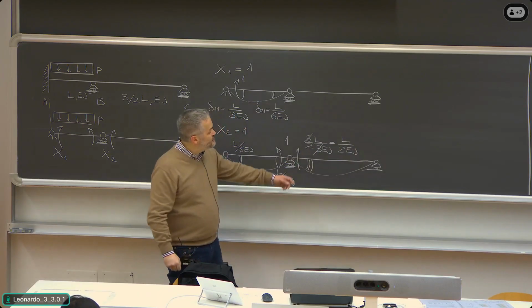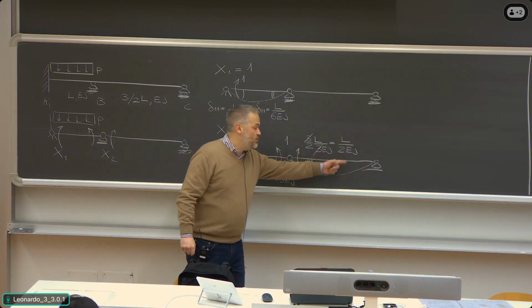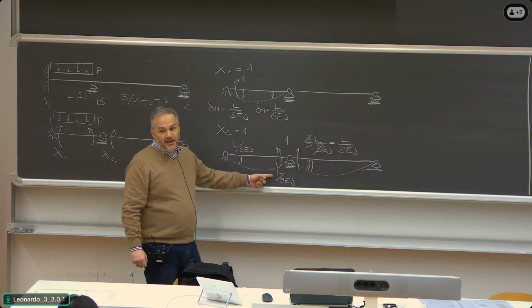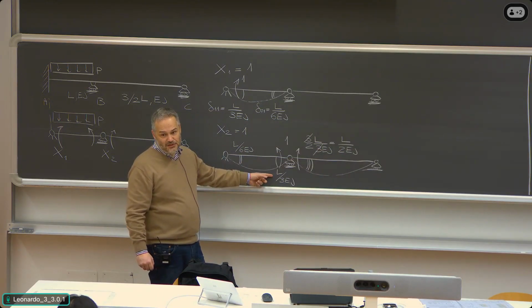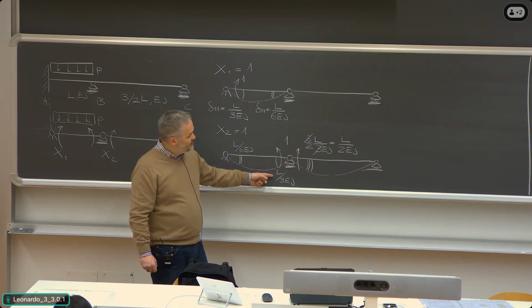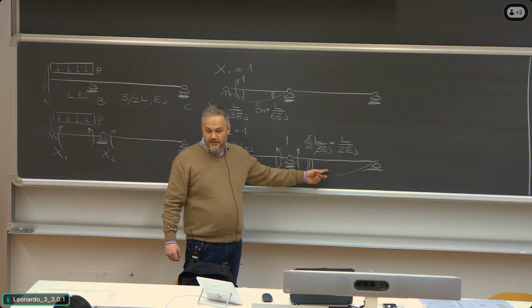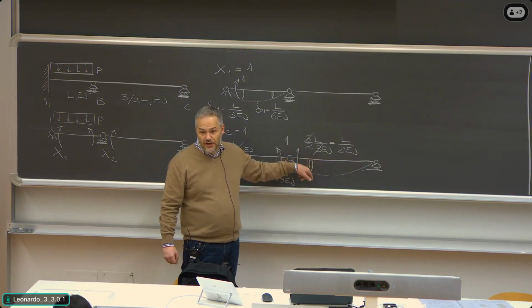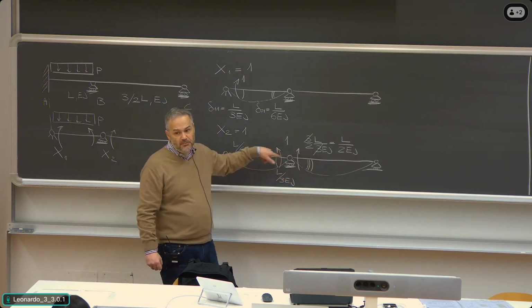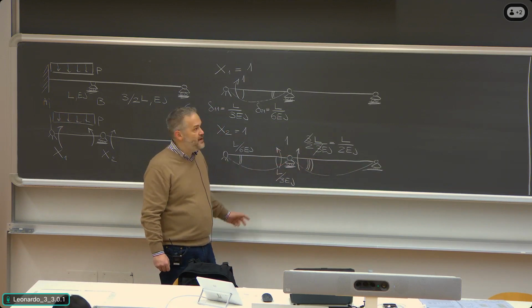Does it make sense to have this rotation, which is larger than this one? Clearly yes, because the stiffness of a beam reduces as the length increases. So the longer the span, the larger the rotations, if the bending moment is the same. Okay?